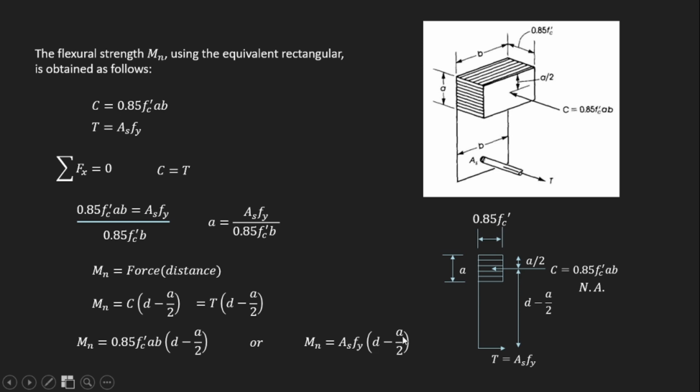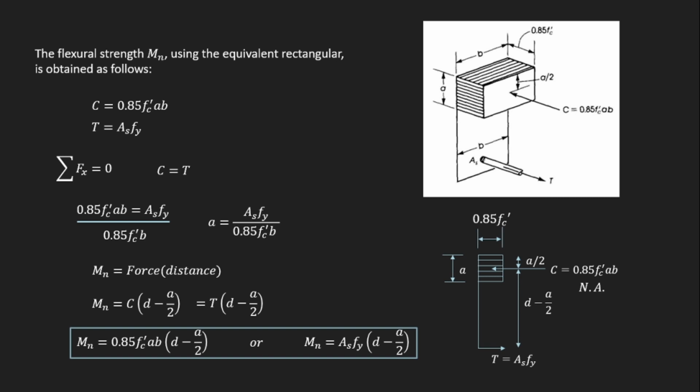And yung A nga natin, pag hindi natin alam, kasi hindi talaga natin alam yan, so gagamitin natin ang formula for A, that is also equal to AsFy all over 0.85 fc prime times b. So just substitute and you can solve the value of Mn. So, this formula, kailangan isaulo yan kasi hindi yan given sa mga exams or even sa board exam.